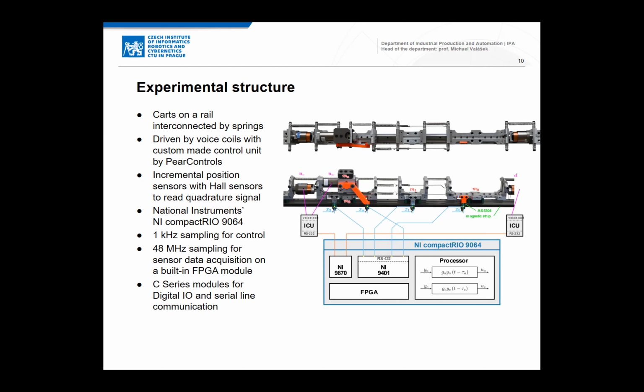We achieved good sampling for control. We run our experiment at 1 kHz for control and data logging, and there is 48 MHz sampling for data acquisition, especially for reading and decoding the quadrature signal of the sensor.